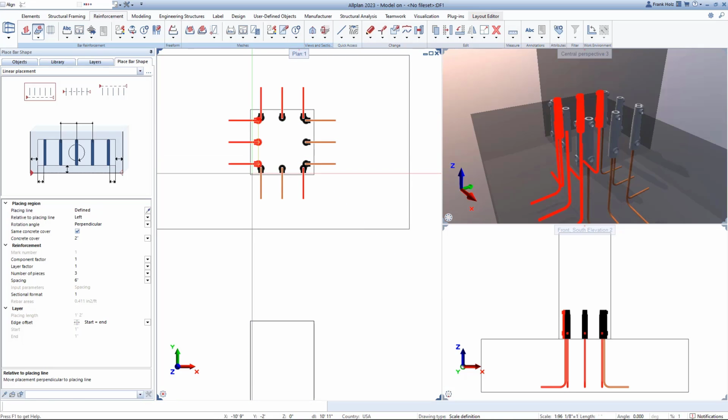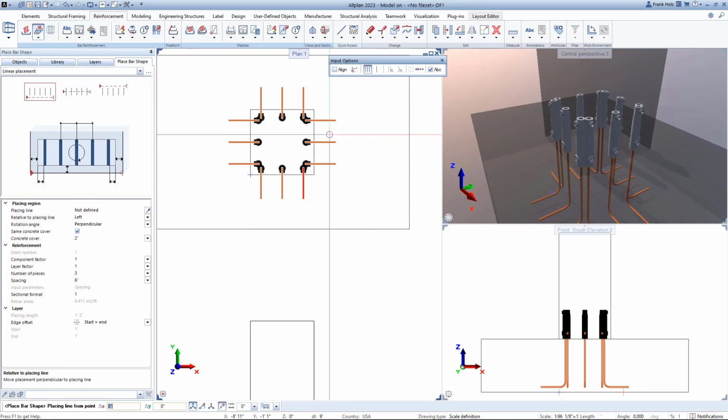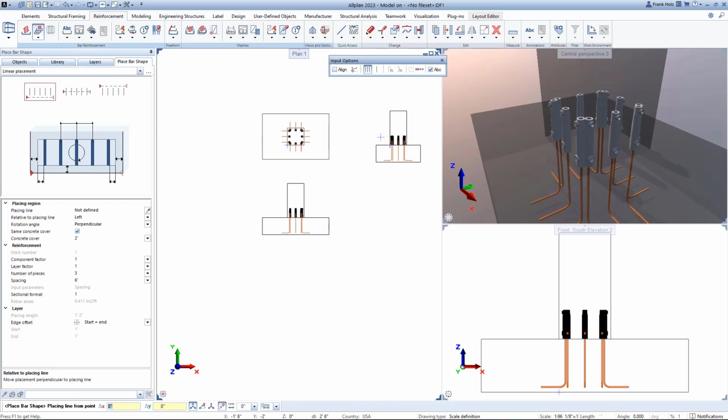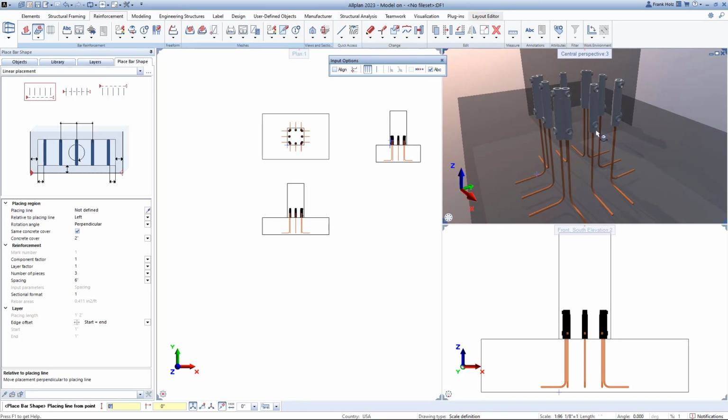So just remember that whenever you create a bar in a section, it always is going to remember that first time you shaped it, where it was, which orientation it was facing. And then whenever I create my grout tube, it'll always face south, and then any additional placements, it's just going to maintain the relative orientation of the coupler to the bar. So that's how you can get these hooks in different directions and get these ports heading in different directions as well.